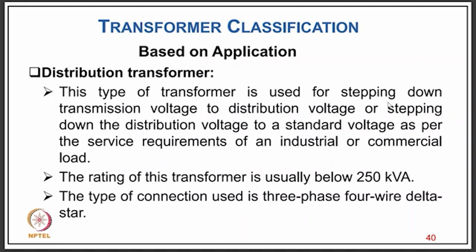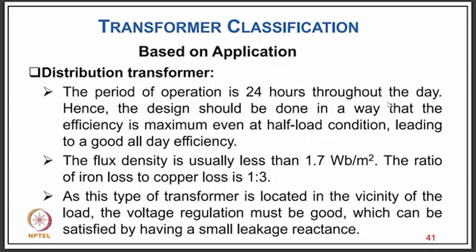single phase distribution. Because of this reason we have to keep the primary in delta; otherwise, on the high voltage side we normally prefer to have a star connection, but here we have a delta connection so that it provides the path for the circulation of harmonic current, and that provides the stable neutral for the isolated secondary of the 4-wire system.